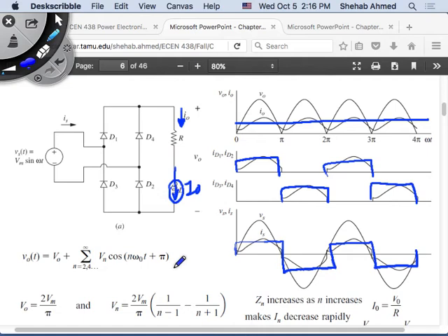It's all your harmonics over your full RMS current, right? THD is a percentage, a ratio between your harmonics squared, all your In squared, divided by your full current squared, right? The sum of all your harmonics divided by the sum of your current squared.